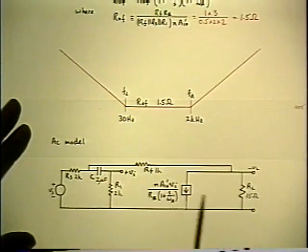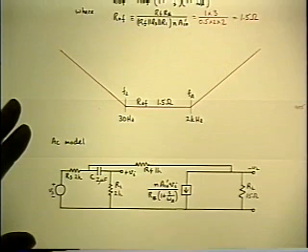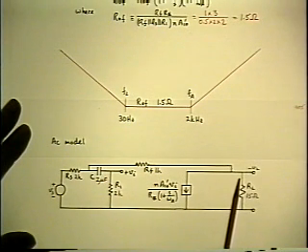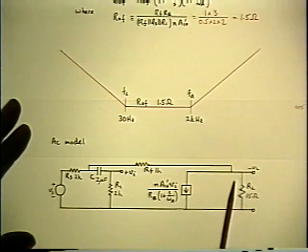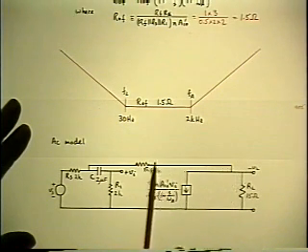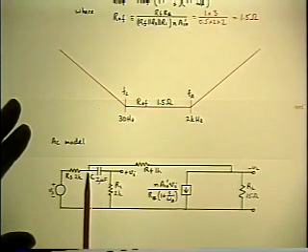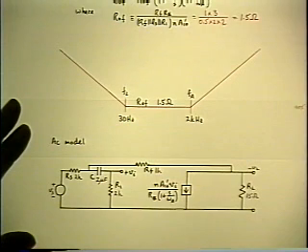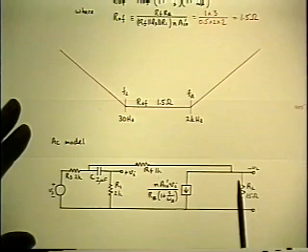That's why you get zero loop gain at infinite frequency as well. So once again, the only contribution to output impedance at infinite frequency would be the impedance of the feedback path itself plus RS parallel R1, because the coupling cap would be a short, which would be 1K plus 2 parallel 2, or 2K. So the output impedance ought to be flat at 2K at infinite frequency.